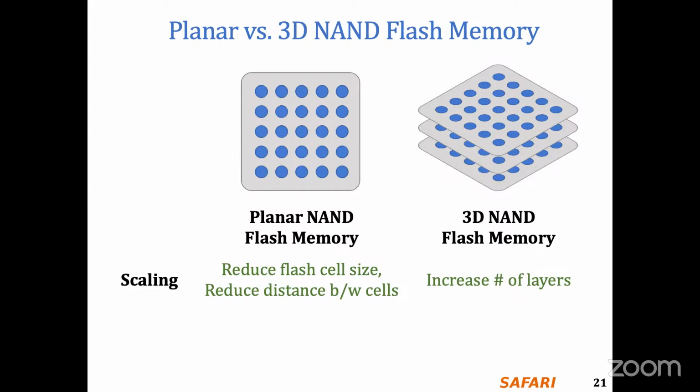At some point, in order to provide higher density or higher capacity, they also need to go to smaller flash cells in 3D NAND flash memory. As a result, you will have more errors. As I said, in this lecture we will mostly see MLC, but nowadays people are using QLC. And with QLC, for sure, you will have a lot of errors, especially in 3D NAND flash memory.